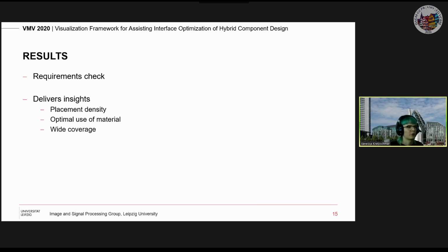And in terms of the positions we can leave free, the results taught us to obtain a wide coverage orthogonal to the load direction and a slightly increased density parallel to it. The only exception to this statement was found on the outside, since narrow pins in the load direction promoted crack propagation, as previous slides showed.